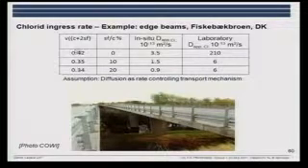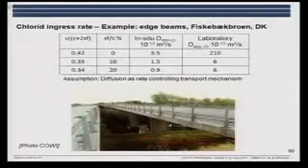So we have some examples here. This is the water, well, it should be W, water to cement plus 2 times the silica fume ratio. This is what is called the equivalent water cement ratio, and it's the efficiency factor 2 which is used for silica fume here. The efficiency factor is discussed in connection with standardization work.